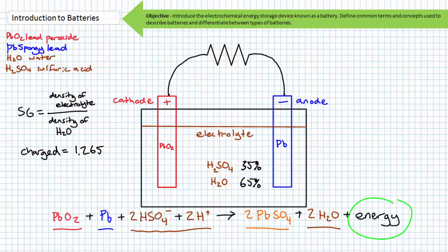A fully charged, flooded lead-acid battery will ordinarily have a specific gravity reading of about 1.265, meaning it is more acidic and less water-like. This specific gravity reading roughly translates into a charged flooded lead-acid battery as having an electrolyte concentration of 35% sulfuric acid and 65% water.